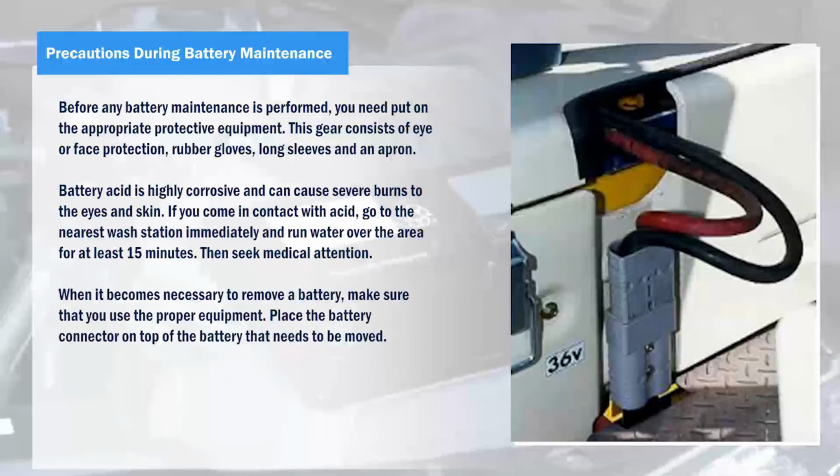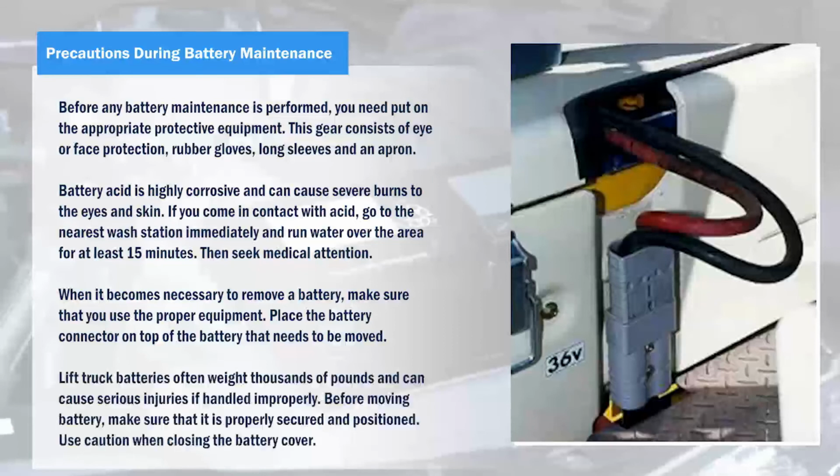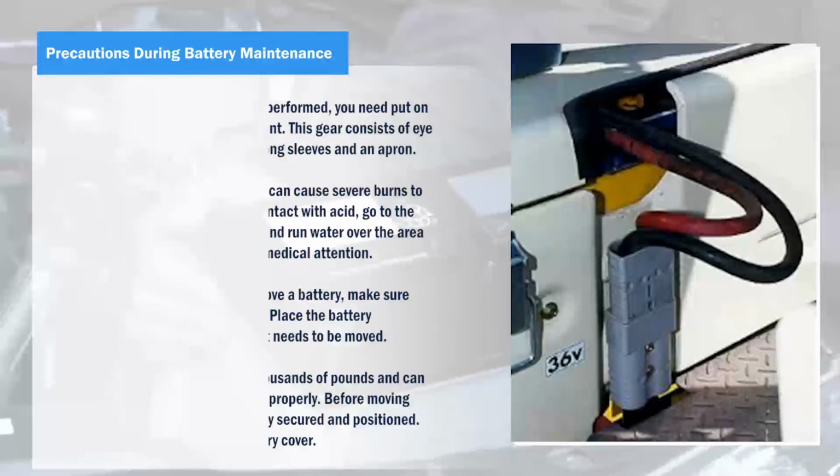When it becomes necessary to remove a battery, make sure that you use the proper equipment. Place the battery connector on top of the battery that needs to be moved. Lift truck batteries often weigh thousands of pounds and can cause serious injuries if handled improperly. Before moving the battery, make sure that it is properly secured and positioned. Use caution when closing the battery cover.